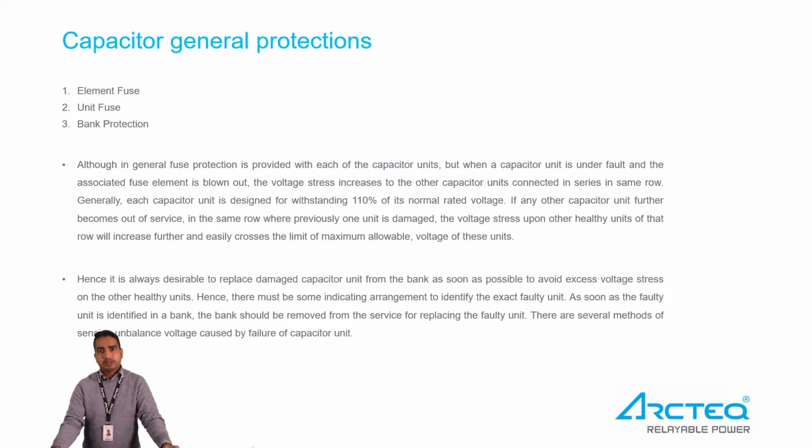The purpose is to use an IED to detect those stresses before the whole capacitor bank is damaged. So we use capacitor IEDs to detect the unbalance that happens due to those fuses removing the capacitors from the bank. So we find out before it damages the whole bank, basically.